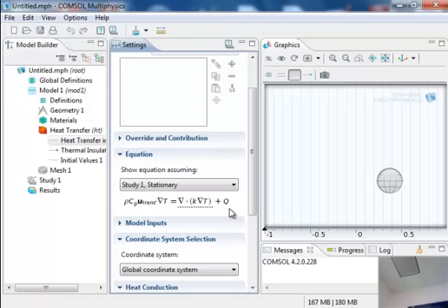Okay, and theta at psi equal to 0 is 1, and theta at psi equal to 1 is 0. That's the case A. This is the equation we want to tell Comsol to solve. But the equation that you see there is going to become like that if I make this 0 by setting the velocity as equal to 0. There's no motion, and I set Q as equal to minus m theta. I need to do those things. If there are any questions, please do ask me.